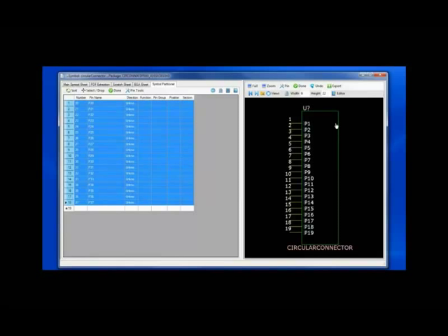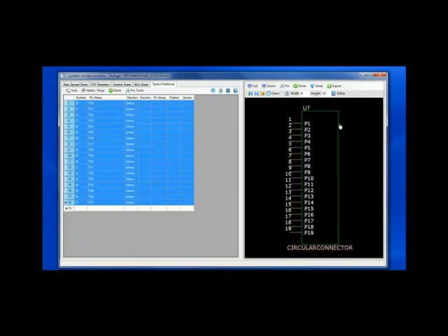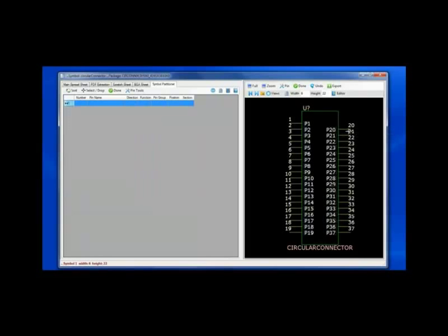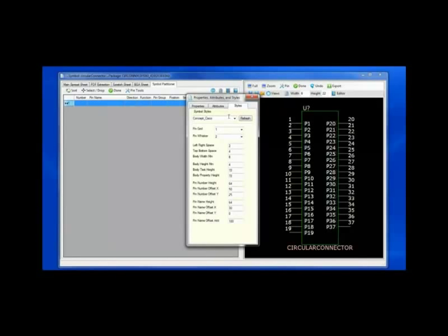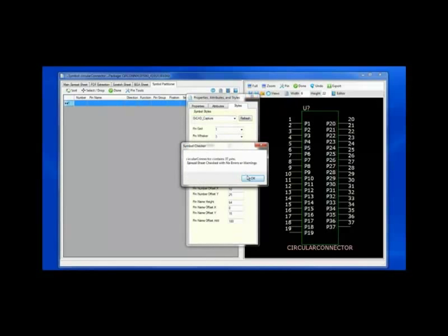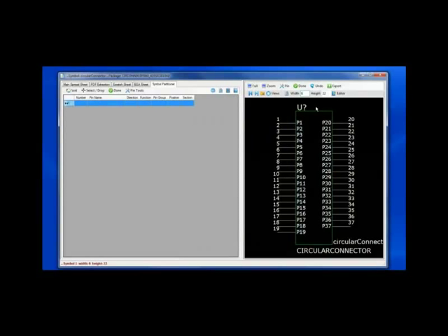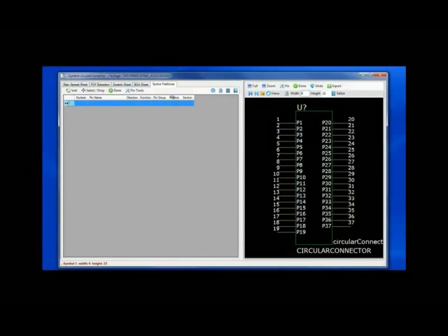Using typical editors, sometimes users will drop pins in the middle. That is not possible with the partitioning manager that manages all of the pins once the symbol set has been checked. You can see how easily I have moved the pins and supporting different styles, for example, corporate styles for individual corporate, or switching the style to ORCAD capture in this particular case with a 3-pin whisker length.